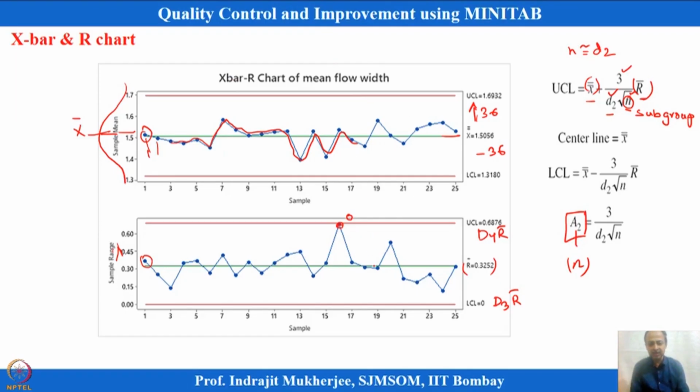Here also we can see that there is no abnormal scenario. So, range, that is variability, is also within the control limit lines over here. So, we can say that this is a stable process, and under statistical control. And so, there is no abnormality observed in the process, and in that case we will continue monitoring like that. We do not have to adjust the process variables or process parameters or process setting conditions. So, let it be as it is.